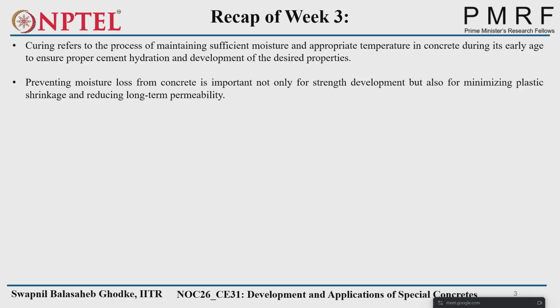If there is more plastic shrinkage, what will happen? Cracks will appear in the fresh state itself, right? To avoid that, we have to properly cure or properly protect the structure from direct contact with the environment.